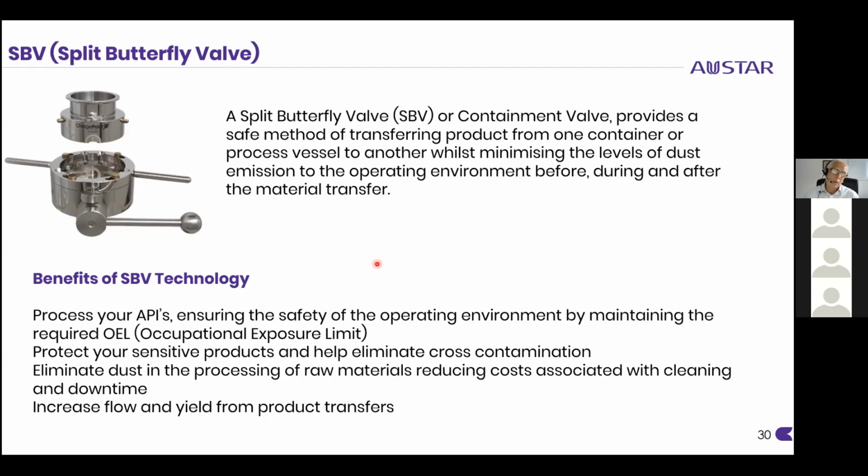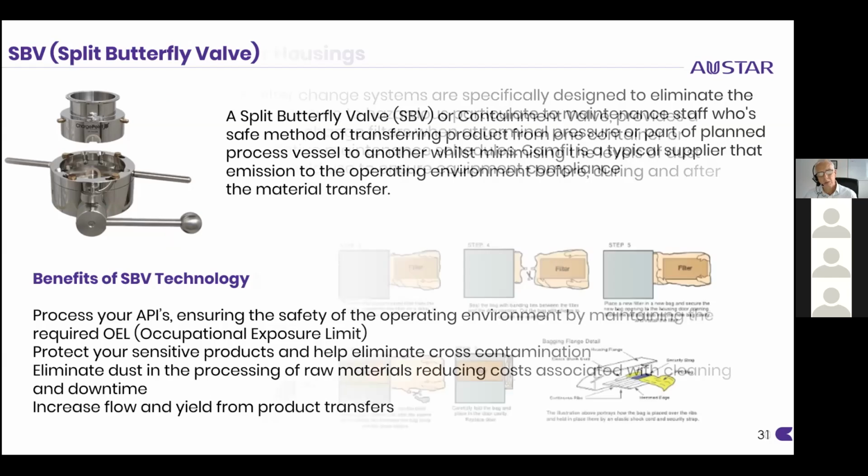Again, the isolator can only be as good as the transfer solution. So when we buy these, we have to ensure that they're from a reputable supplier who has done their own containment testing, and they guarantee that their split butterfly valves match the OEL of the product. Again, an important part of the risk assessment.